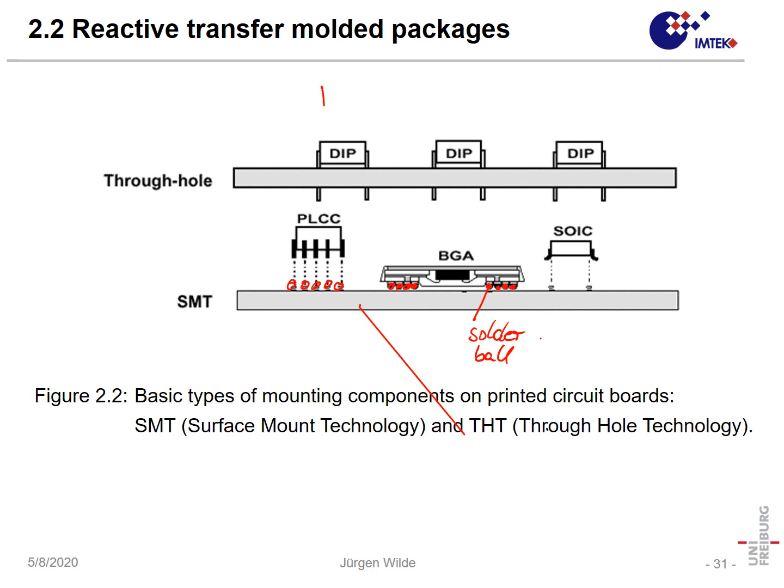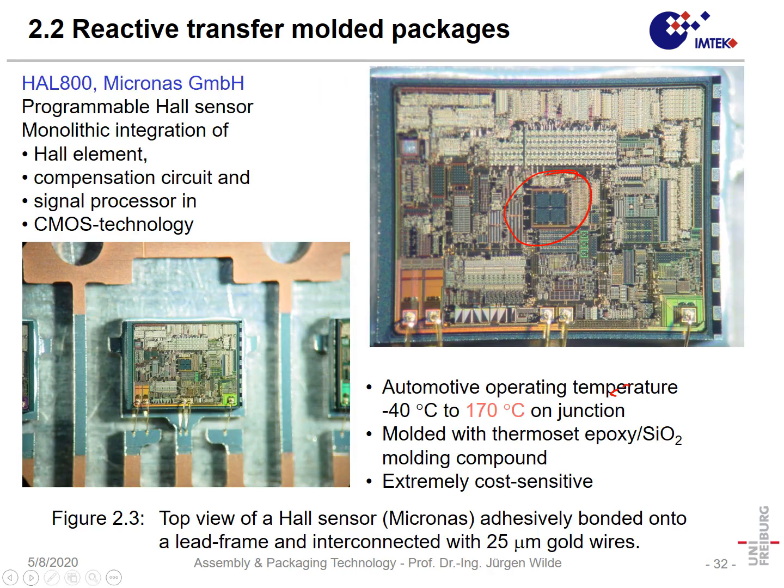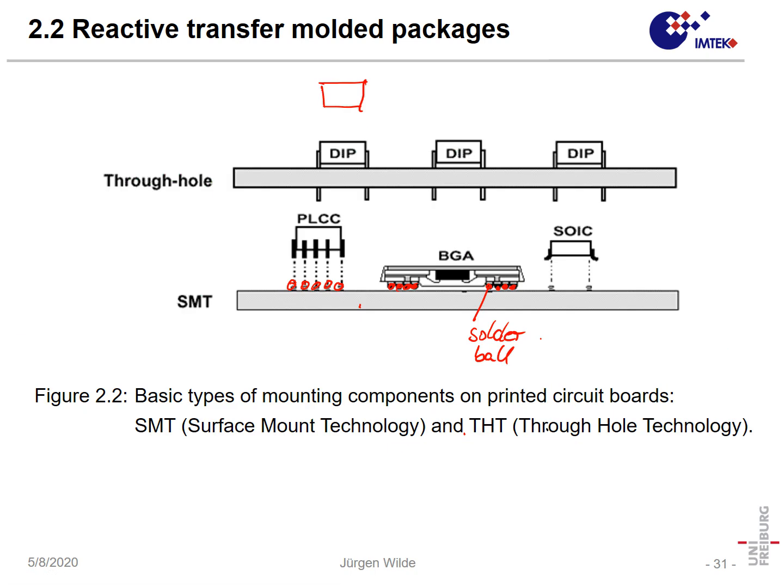You must have a machine which puts your device into the printed wiring board. And now imagine you have 100 very flexible pins, and one pin is bent only a little, and you want to press it with an automatic machine into these holes, then you will have a big problem.